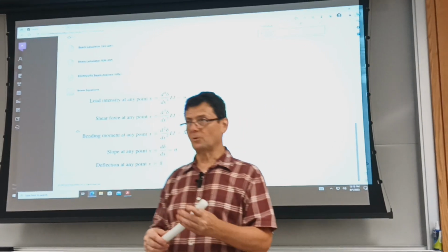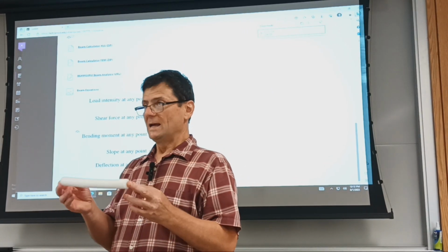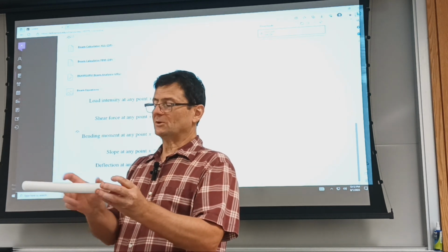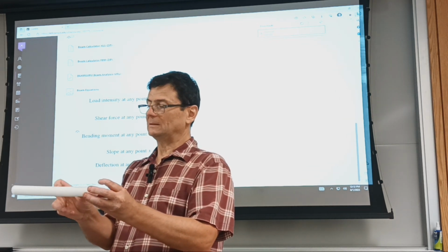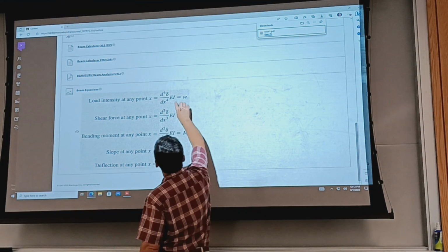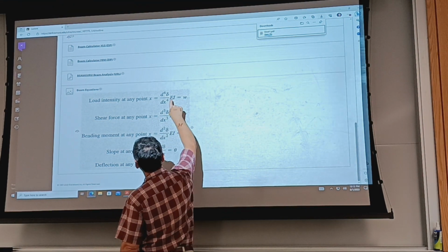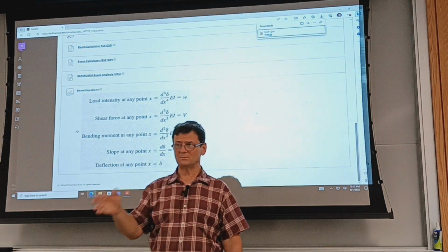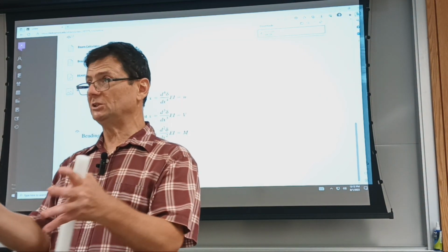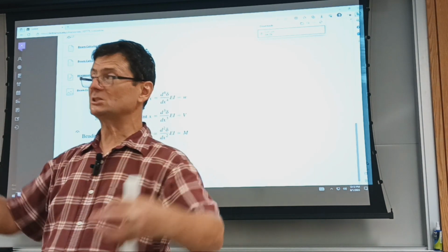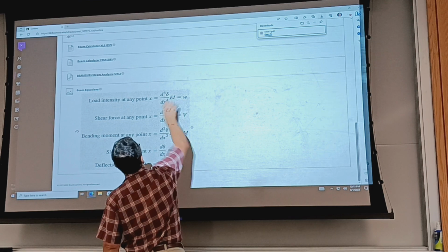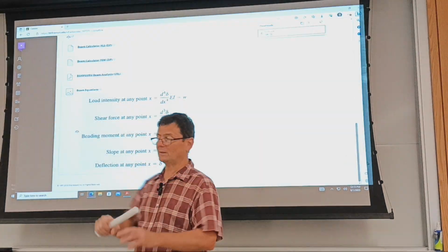If you look at the homework problem, some of them have different moments of inertia. The beams, as fabricated, usually have a section in the middle where you increase this term, so this term can vary. You can even have I changing along the beam. So if you have a middle section that is one material, and then you weld or braze to it a different material, although that's less common.